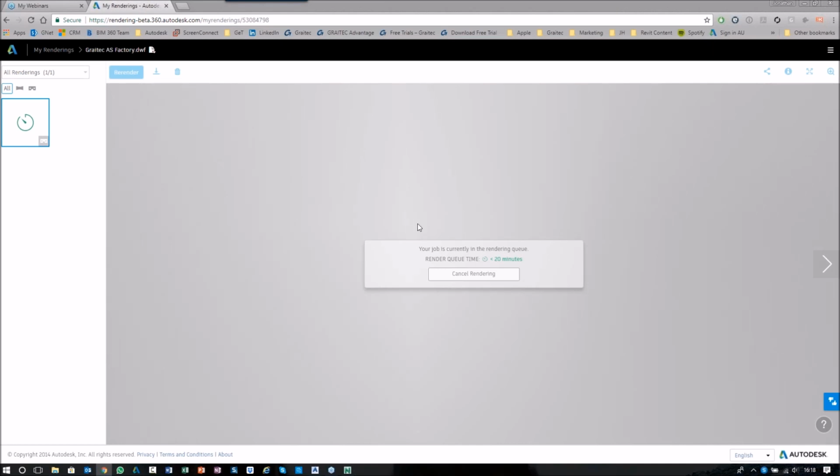So I've just got a question. Can you show individual members being installed within a selection set to show a more realistic construction process? Or would you need to select the members on their own? You would need to select the members on their own and then just save that as a selection set. You can't drill down in the selection set. So if you were doing individual members, it would just take a little bit more time in terms of the selection set, because it would be a selection set for each one.